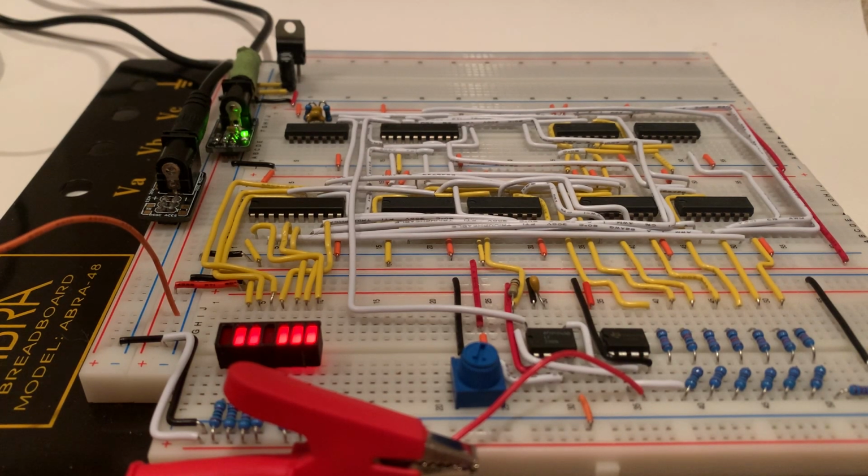With the demonstration of the working circuit, let's go to a bit of an explanation of how to interpret this result, because it may not at first be very clear. This resultant binary number can be thought of as a fraction out of 127, because the highest possible value on the output is 1111111, or 127 in decimal.